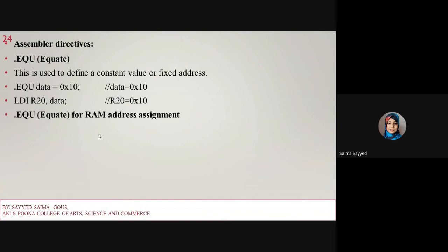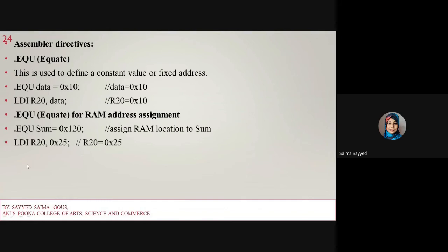It is also used for RAM addressing assignment in this manner: .equ sum is equal to 0x120. So this assigns a RAM location to sum. That means whatever the data in sum, it will get loaded to this particular location, that is 0x120. We will see one example.